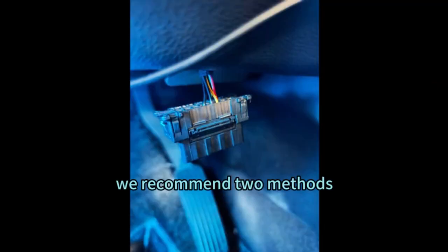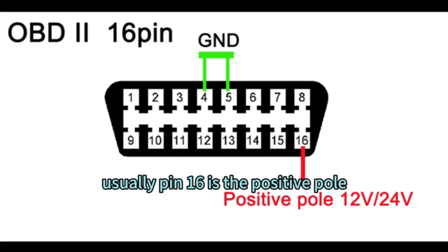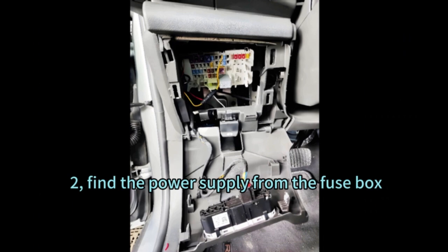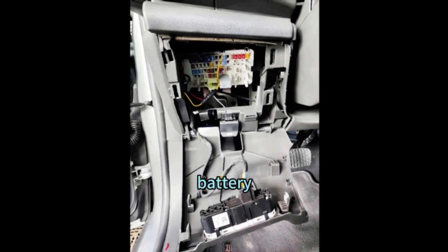We recommend two methods. One is the 16-pin OBD interface. Usually pin 16 is the positive pole. You can connect the wire behind pin 16 to the device red wire. 2. Find the power supply from the fuse box. As long as the voltage is the same as the vehicle battery when ignition is off, it is fine.